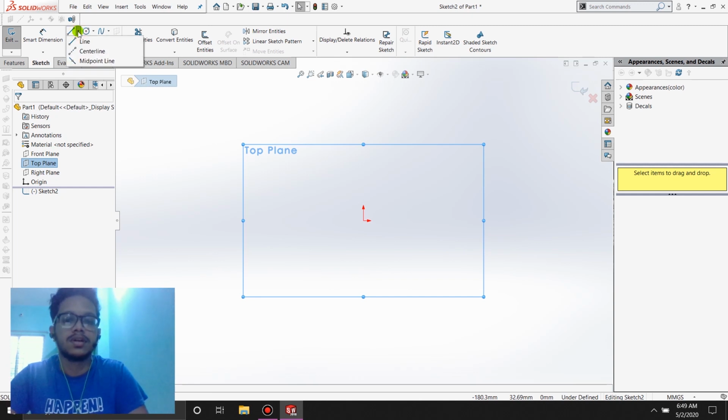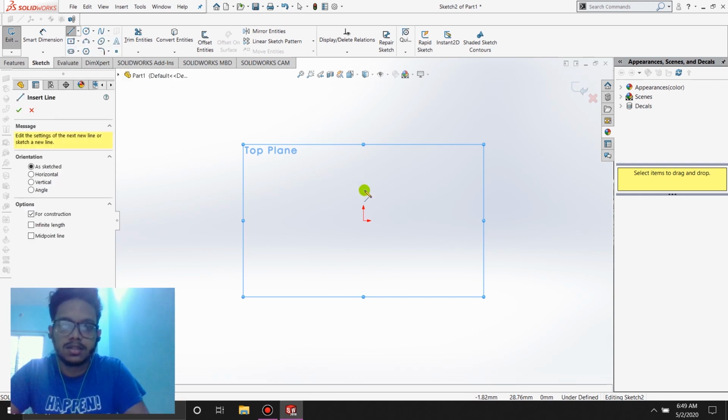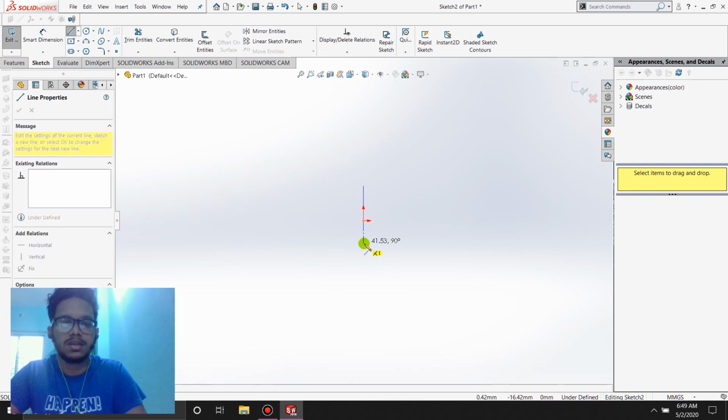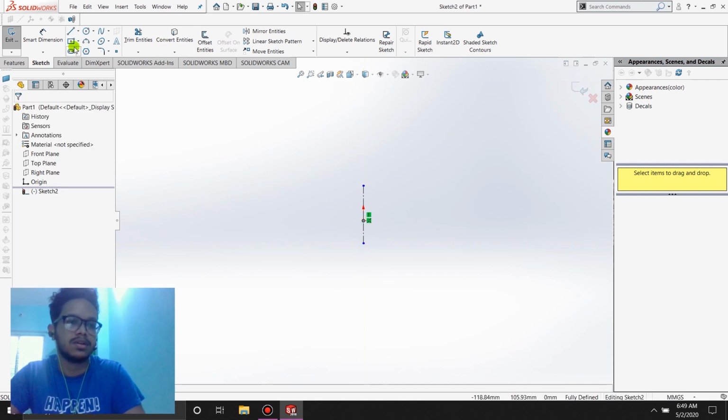So first of all, whenever you design, you have to start with the center line. It's good to start and make a center line. Okay, it's not going to draw a sketch on whatever you're designing, but it's good for keeping an accurate measurement. So let's just keep a center line here. We click escape. So there's our center line.